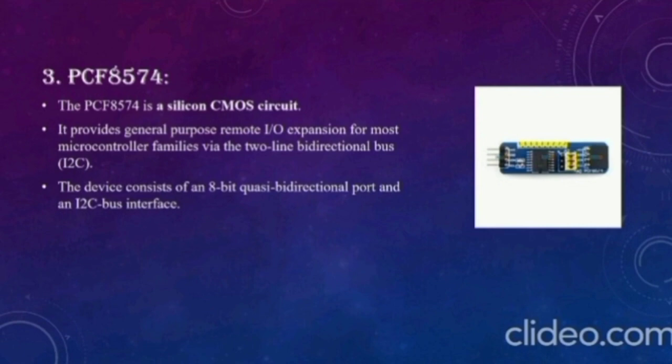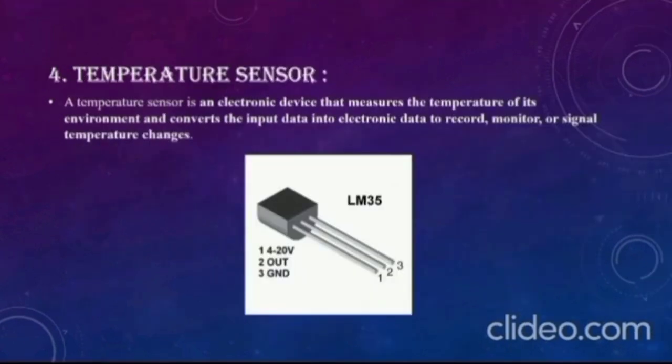Third one, PCF 8574. The PCF 8574 is a silicon CMOS circuit. It provides general purpose remote input/output expansion for most microcontroller families via the two-line bidirectional bus. The device consists of an 8-bit quasi-bidirectional port and an I2C bus interface.